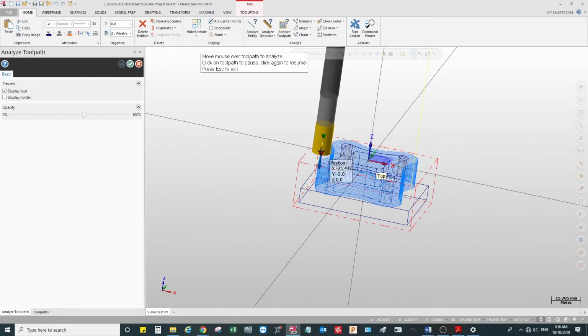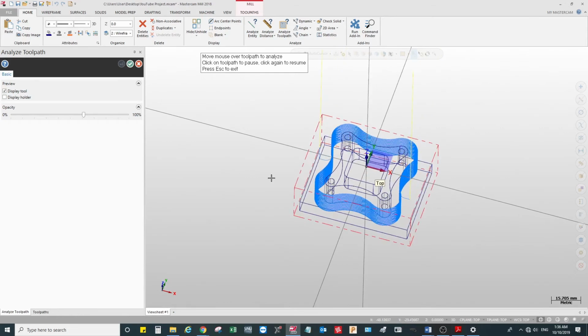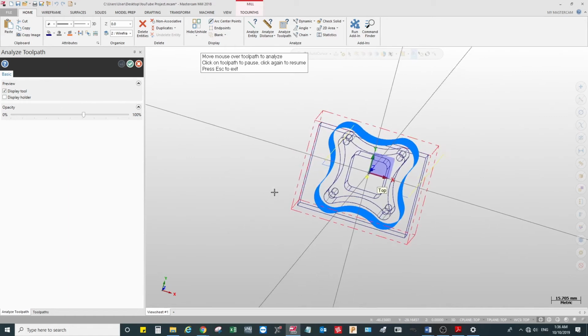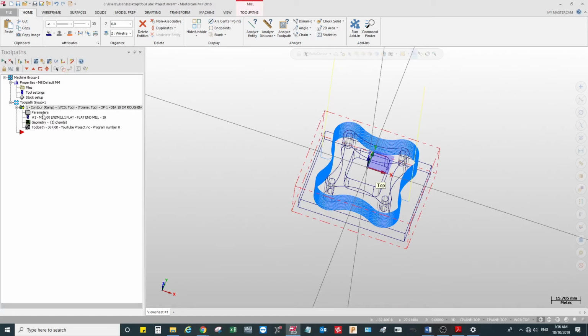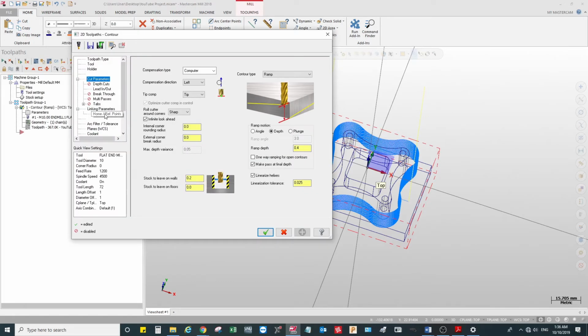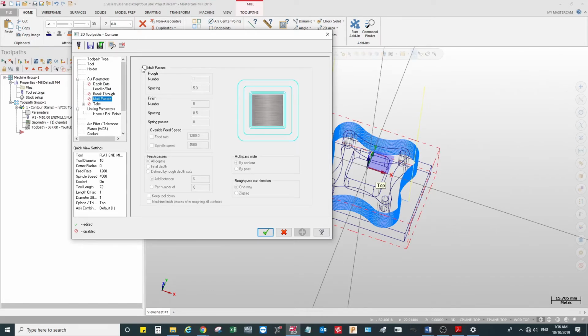All right, I've fed in all the parameters and information, and before clicking on the OK button, I can visualize what my toolpath would look like, so I can have a preview of it. Now I see there's a bit of a problem. The toolpath is inside, so I'm going to change it to left. I'm going to go with climb milling. That's what CNC machines are good for. Once I click on preview toolpath, it gives me the toolpath that I really wanted.